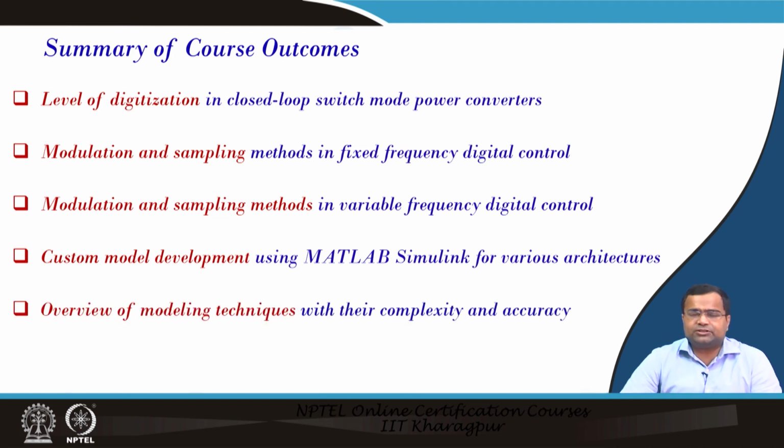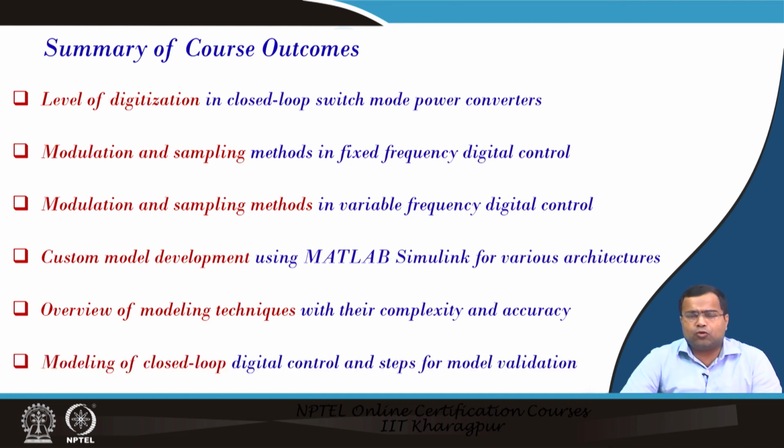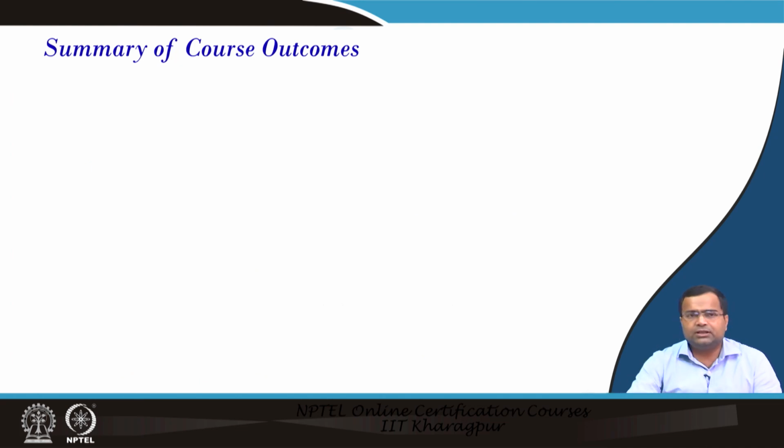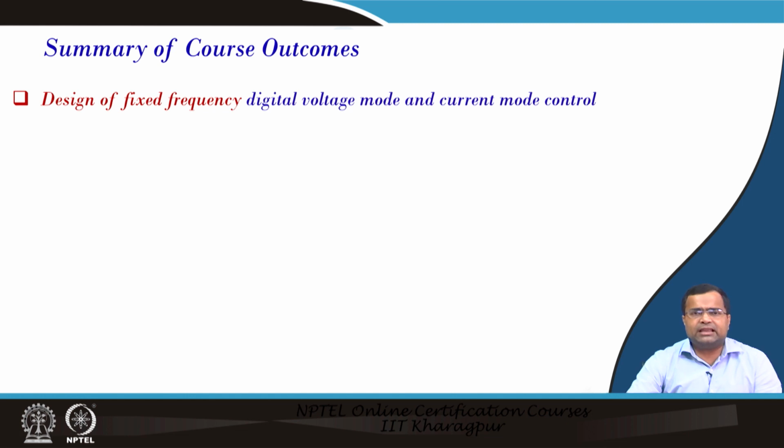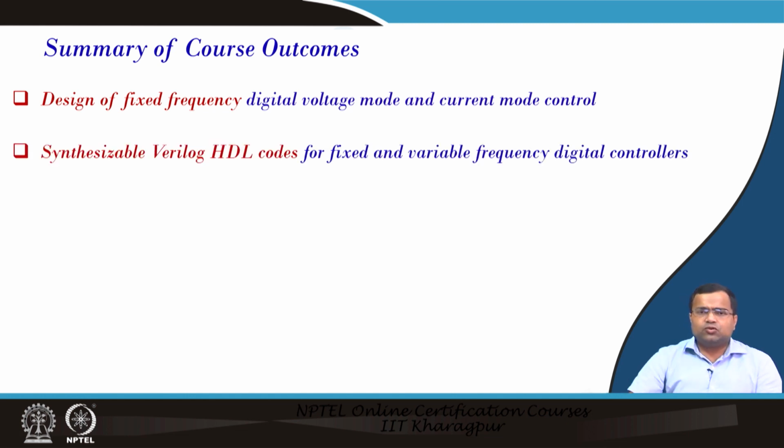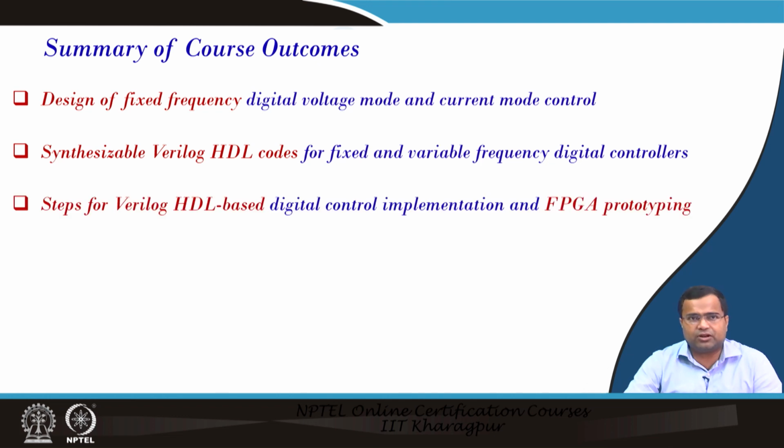Then we have discussed an overview of modeling techniques with their complexity and accuracy aspects. Then modeling of closed loop digital control and the steps for model validation. We have also discussed the design method for fixed frequency digital voltage mode and current mode control techniques. We have also developed a lot of synthesizable Verilog HDL code for fixed and variable frequency digital controllers.